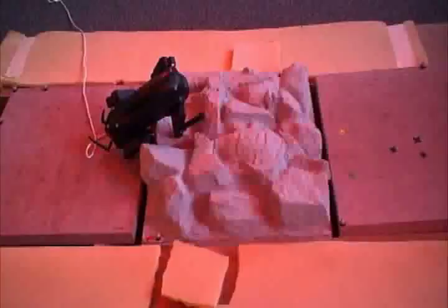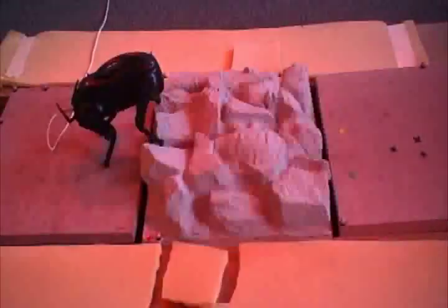Due to unmodeled large-scale features, the dog may fail as shown in the first trial in this video. To account for this, a trial-to-trial learning algorithm remembers bad footsteps and avoids them in future trials, enabling the little dog robot to cross the board after a few attempts.